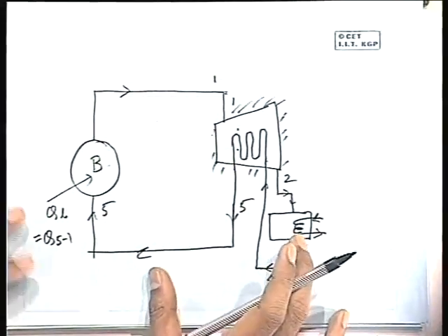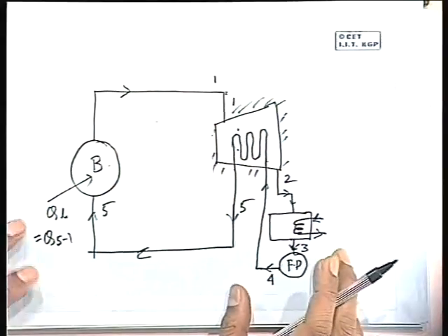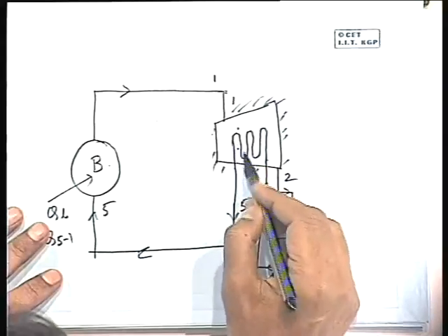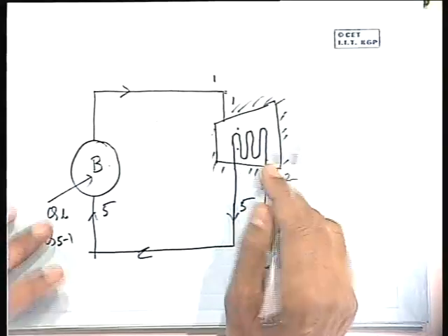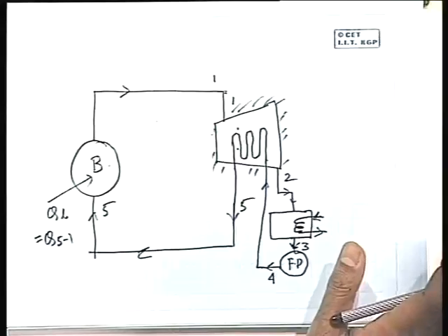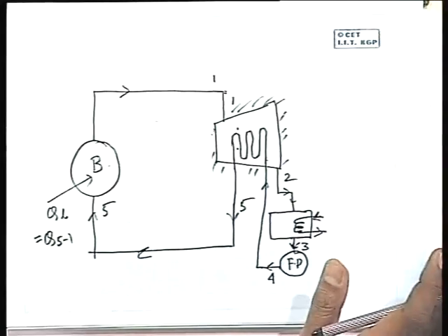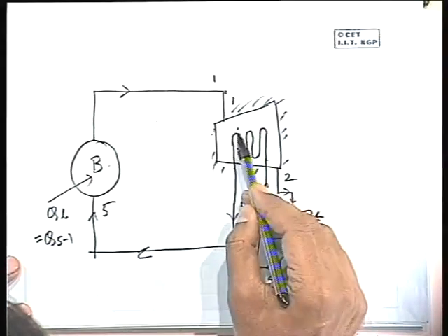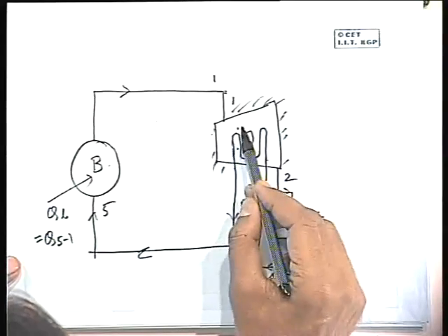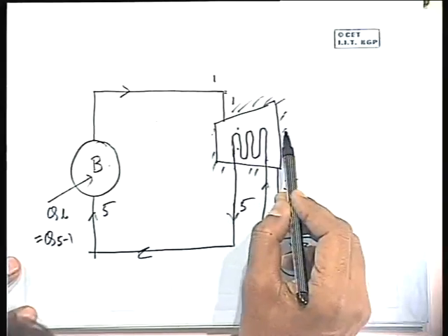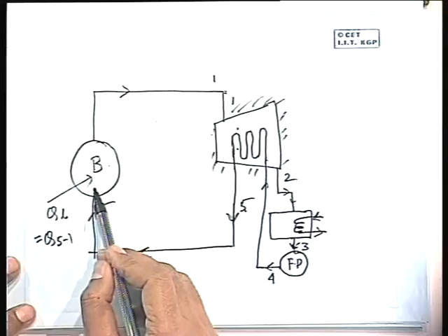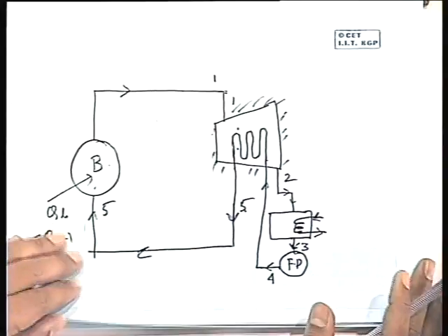So this is the block diagram of the component that we envisage this way. But the question immediately comes, how can I put a coil of this type as a heat exchanger into a turbine that comes afterwards? Definitely no. But to understand the concept or the philosophy of regeneration, we think as if the water is allowed to pass through the tubes or through the condenser, where it can exchange heat directly with the expanding steam, to be heated to temperature 5 and then comes to the boiler. So this is conceived in an ideal regeneration process.